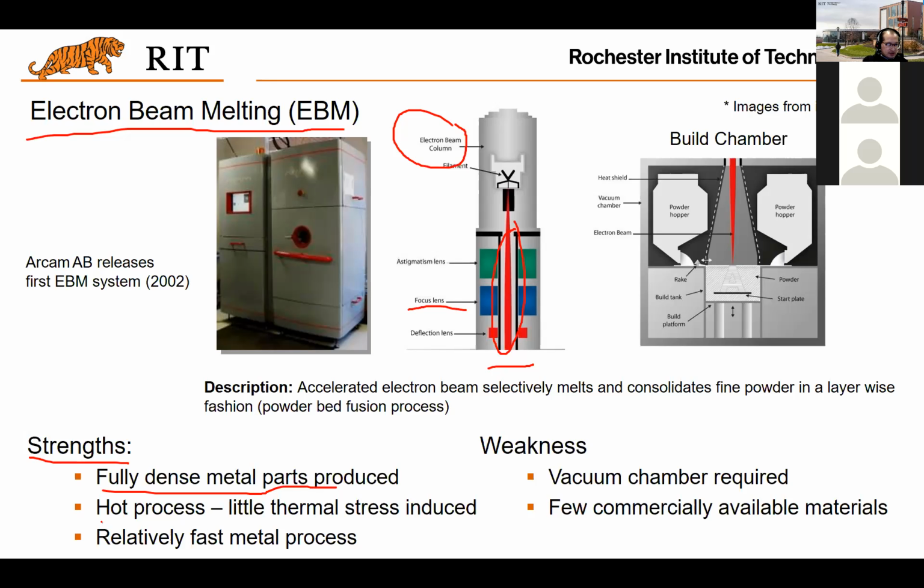It is a hot process, meaning the whole powder bed needs to be heated up so that during printing, the temperature difference between the environment and the parts, I mean the powder, is minimized, and little thermal stress will be introduced.